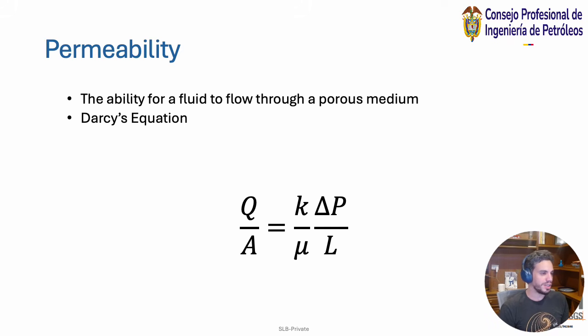One thing to note here is that if you break it down in its most simple form, fluid mathematically can only move if the change in pressure exists. The flow Q can only have a number greater than 0 if the delta P is greater than 0. And that is something easy to understand. It's relatively intuitive. You've played around with it as a kid when you had a straw with some liquid and you put your thumb there. You're kind of negating the pressure, and that's why it stays and doesn't fall. You're not defying gravity. You're just basically applying Darcy's law of making that delta P close to zero.